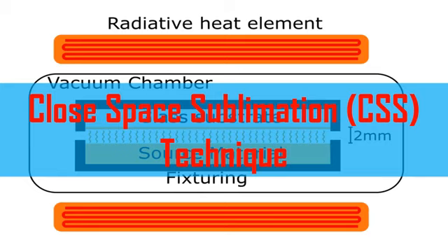Substrates are slightly heated above room temperature, from around 200 degrees centigrade, 300 degrees centigrade, or even 500 degrees centigrade. This heat may also increase the diffusion of the deposited film on the substrate. So there is a diversity of machine designs for the close space sublimation process.